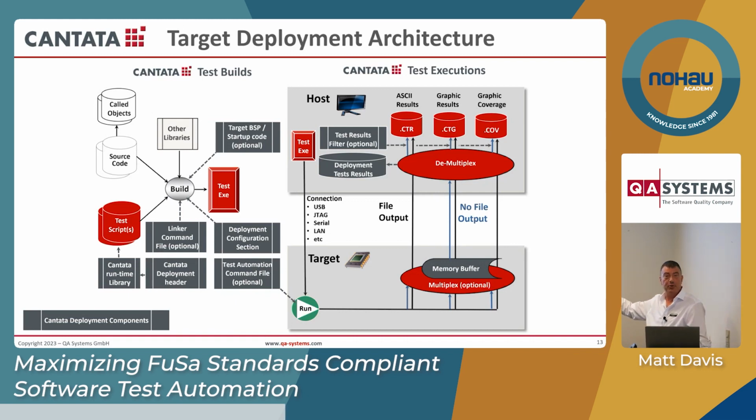In most cases, people don't. They're not running on a full fat RTOS. They're running on a bareboard or a microkernel or whatever, in which case we use lots of different mechanisms to take the data back from the target to the host. Memory buffers can be flushed. We can use different types of connections, basically the way you would work if you are getting any analytics back from your target. And when I mean target, I don't just mean a physical board.